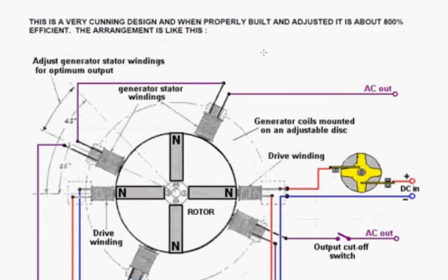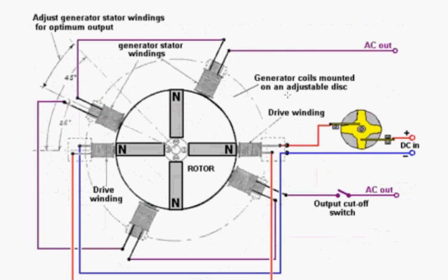The highest powered version of this that I've ever heard built and described outputted at 32 kilowatts of energy, which powered both a business and a household for the person who built it. Now, the thing is, it has got 4 rotor magnets. They're long magnets. The south poles are kept in the center of the rotor. The north poles are on the extreme outside of the rotor. The drive coils and the pickup coils have got solid iron cores.